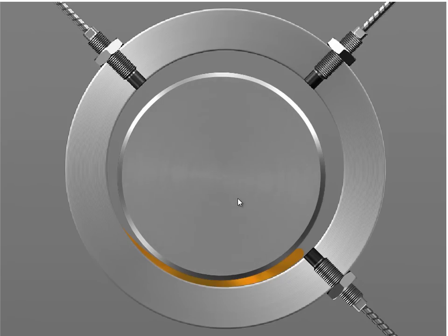So here is what's happening inside these machines. You've got the journal bearing itself. There's the bearing part with the special metal, and here's the shaft, or where it is inside the bearing, we call it the journal. Sitting underneath this is a wedge of oil that forms. So we pump the oil in, that keeps it supported, keeps it stable, keeps it cool, all sorts of good stuff. But unfortunately, if we've got some unbalance or whatever is causing the shaft to move, that vibration doesn't transmit well through the oil out to the bearing, and so therefore an accelerometer may not pick up what's going on.